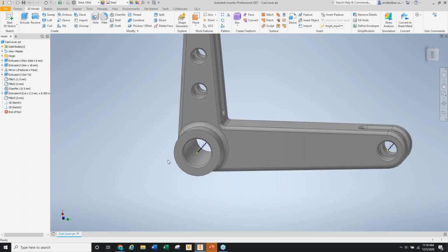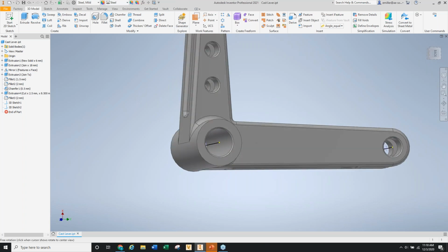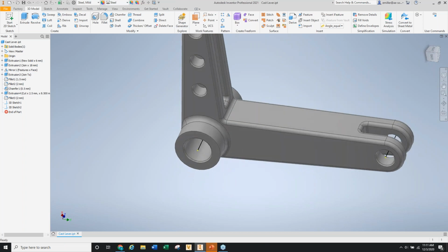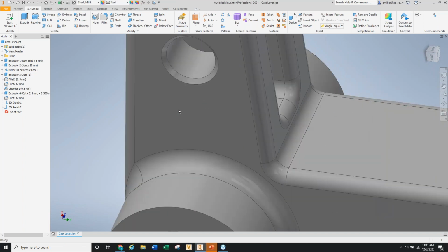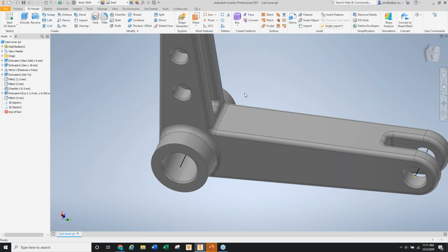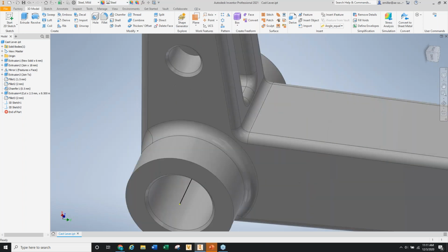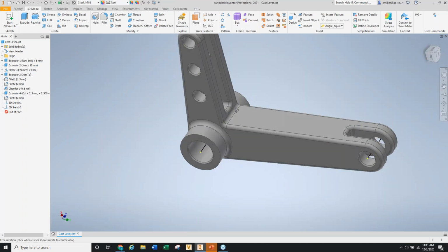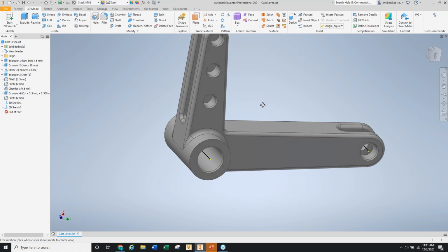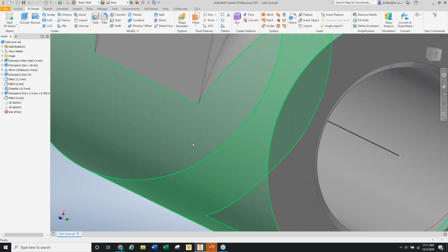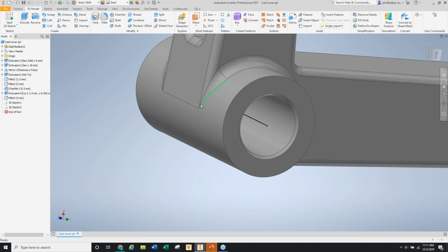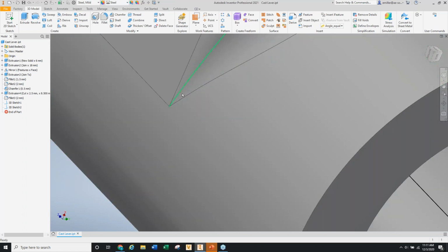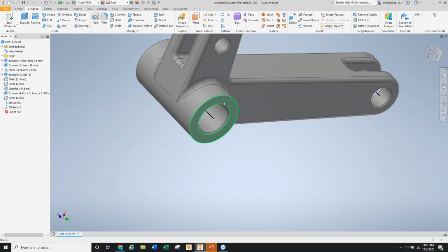So we've got to decide, okay, is this going to be strong enough? It looks like they put nice fillets throughout, so that's a nice way to spread out forces. But we can also try to simplify the model at times. Sometimes with fillets you get a few more mesh elements, and we want to make sure we don't see any sharp corners potentially. Even right here, this is a fairly sharp corner, so maybe there will be a stress singularity at that point. It's hard to mesh sometimes across small surfaces like that.